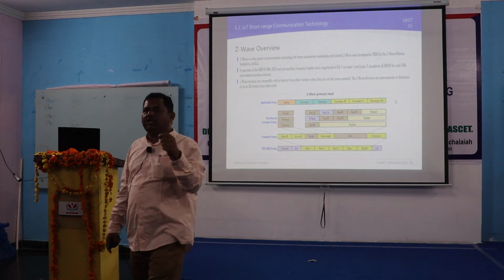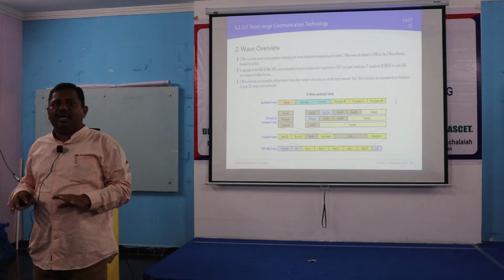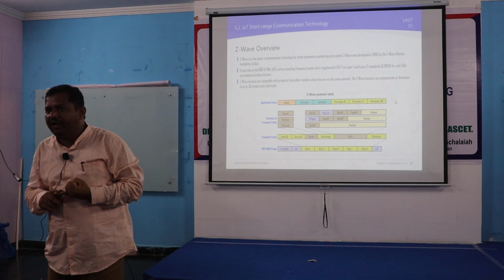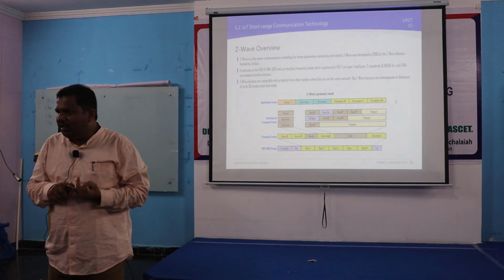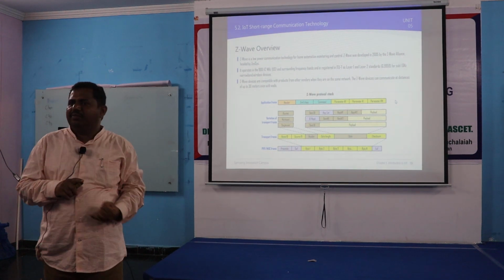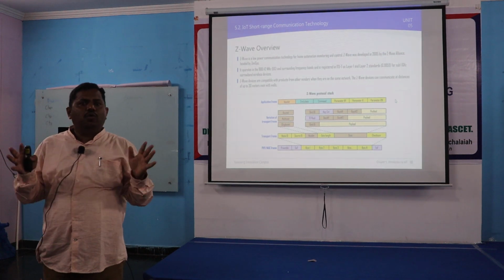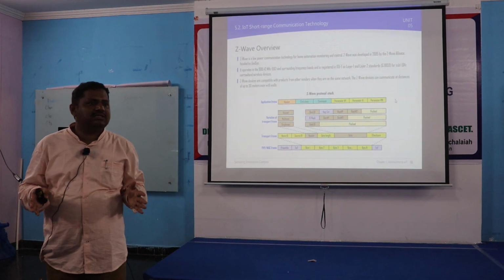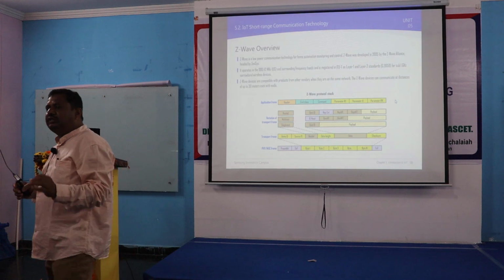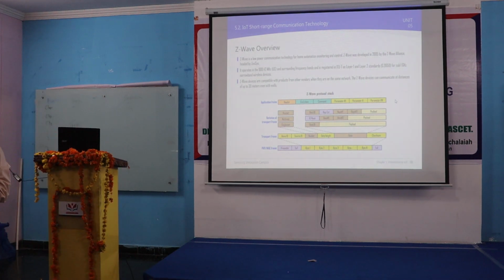Whatever communication you would like to have, currently we cannot use any licensed frequency for Wi-Fi, Bluetooth, BLE or Zigbee. Everything is based on the open frequencies we call the ISM band frequency, the Industrial, Scientific and Medical band, which is license free. But Z-Wave is not license free. It needs a permanent, purchased license of the frequencies.